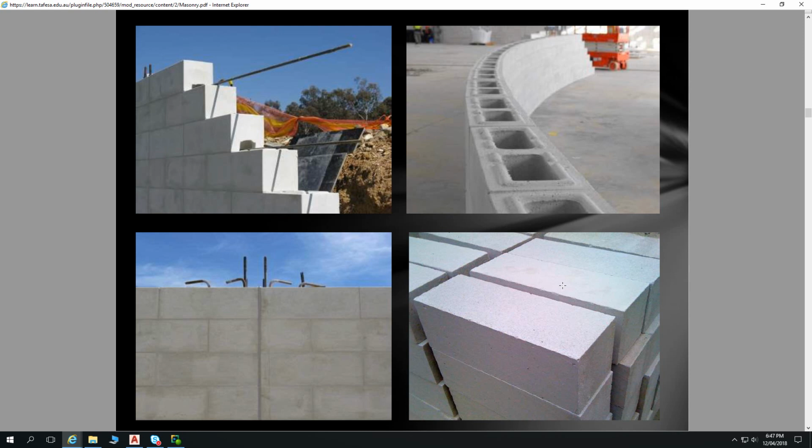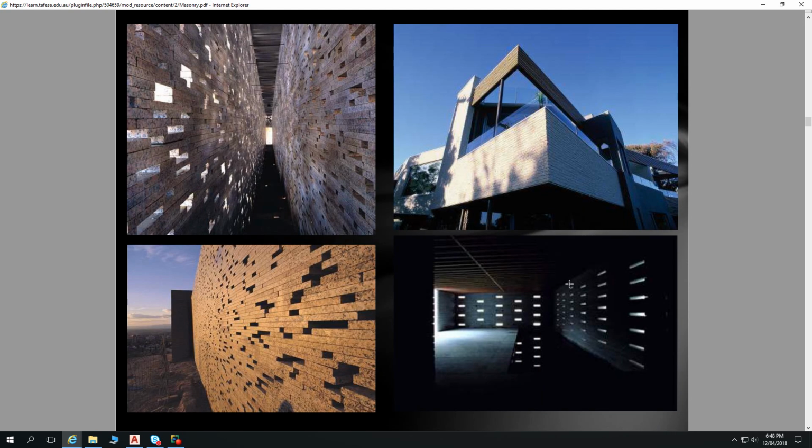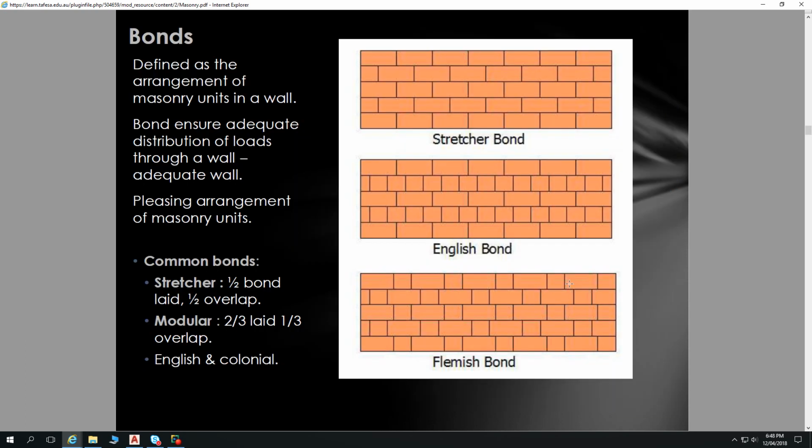Every sixth hole you will fill with concrete and have the reinforcing running up there to create piers within your wall. And I guess that's what's happening here in this scenario. That they've got reinforcing poking up over the Besser blocks there, and they probably core filled those. So they make a very good, easy formwork for the creation of those concrete piers and integrating those piers into a wall. Some groovy stone architecture, brickwork.